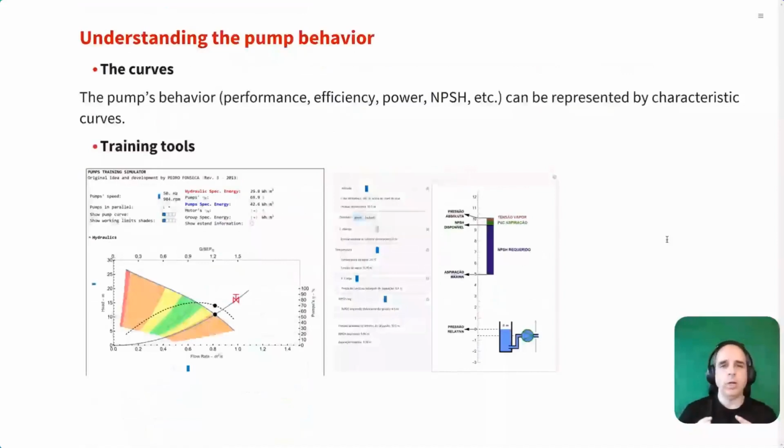So we are going to talk about pump performance curves and how they integrate into a system design, and so we need to understand a little bit of the internals of the engineering of a pumping station. Typically a centrifugal pump is characterized by its performance curve, the relationship between the flow rate and the head that it develops, or let's call it the pressure that it develops.